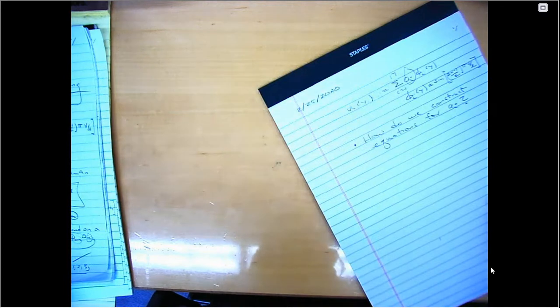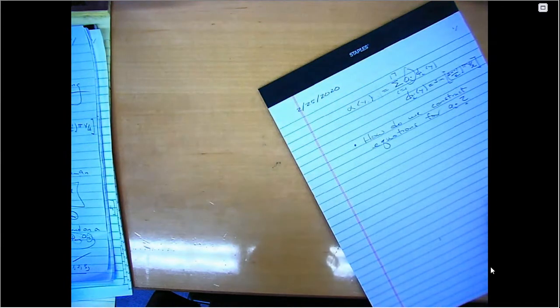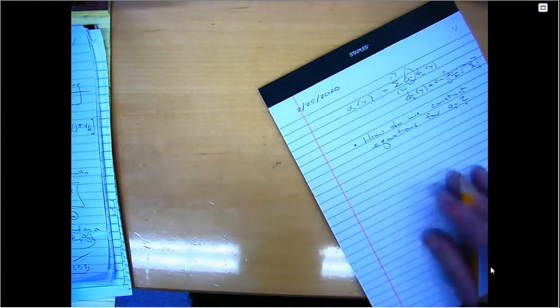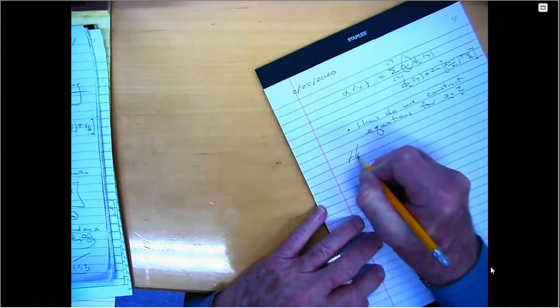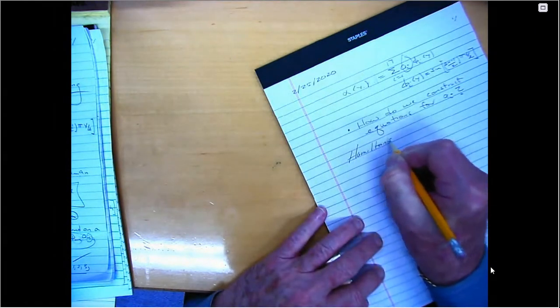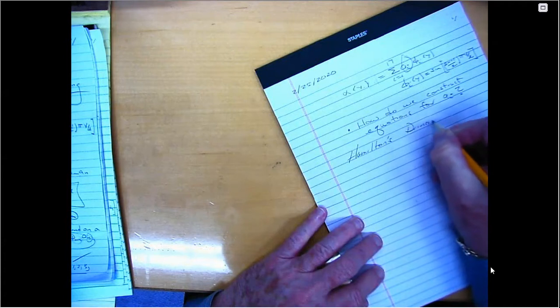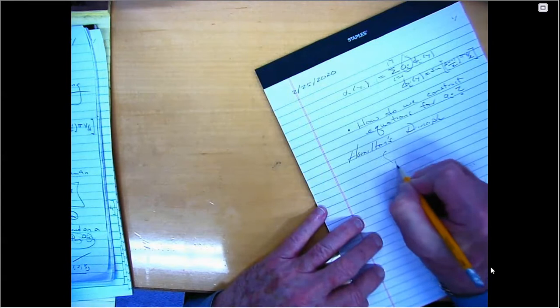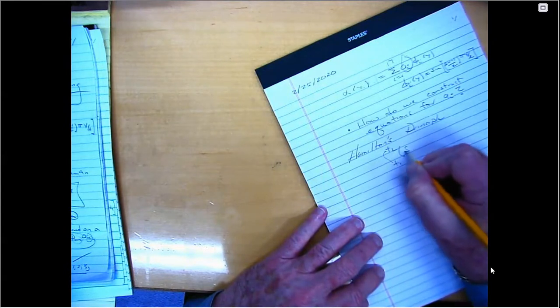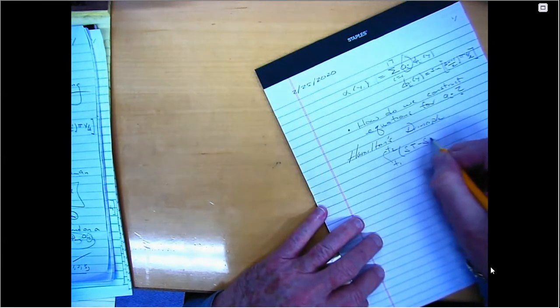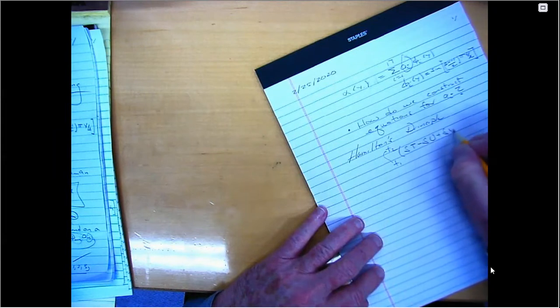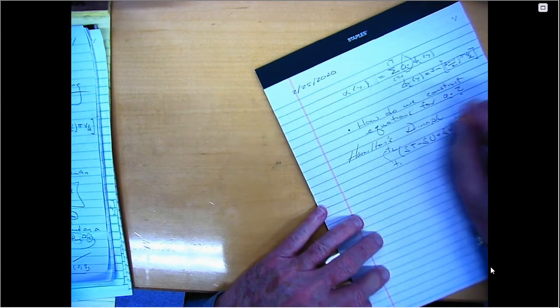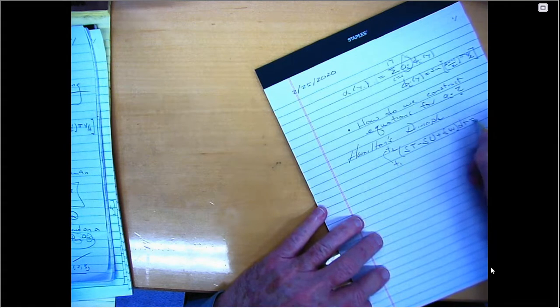Well, now that we're this far along the course, I'm going to take the perspective of the dynamicist, and from the standpoint of the dynamicist, statics is just a special case, right? So that means I could use Hamilton's principle. And Hamilton's principle would say the following: the integral from T1 to T2 of the virtual change in kinetic energy minus the virtual change in potential energy plus the virtual work dt equals 0. Okay?